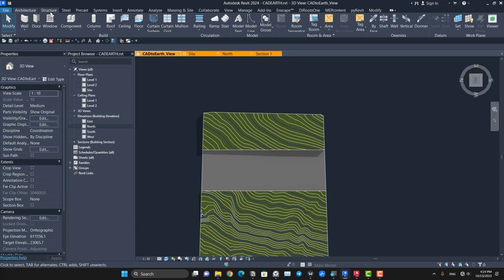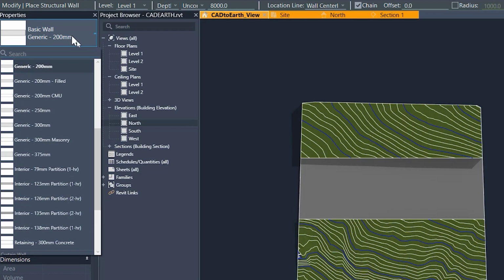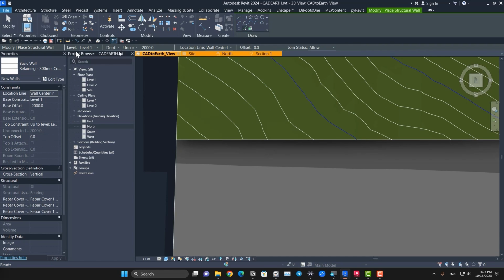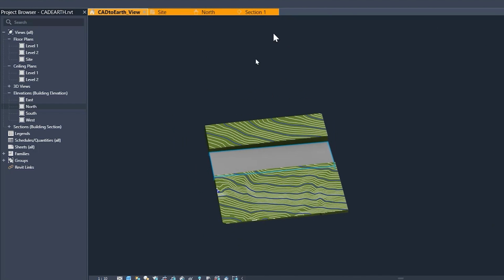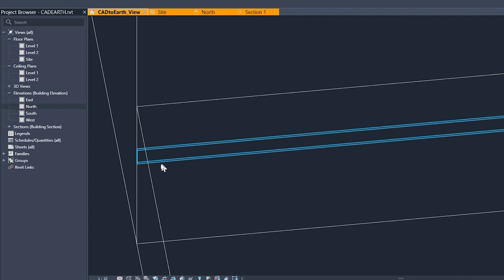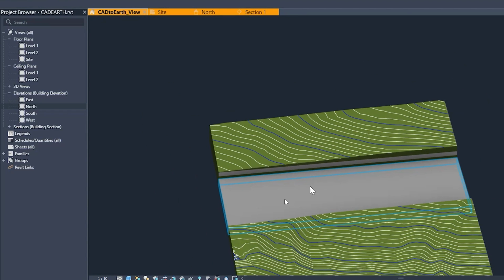Let's go to the Structural tab, and in here let's click on Wall, and let's select a retaining wall in here. And now let's just go to the pick line with the height Level 1. I will specify the height later. And let's go to wall face exterior. Let me zoom a little bit. And we have the wall in here. The wall is not visible in here. This is the wall right now that we've created. It's very small. Let me bring it up, and let's go back to the file that we had.